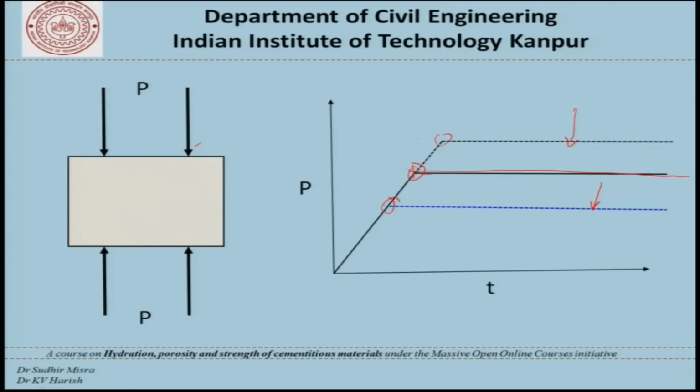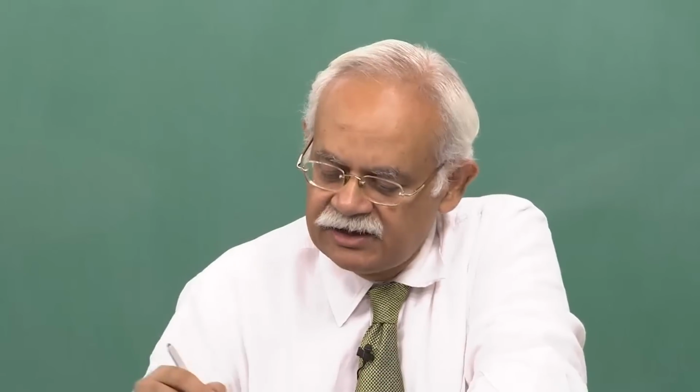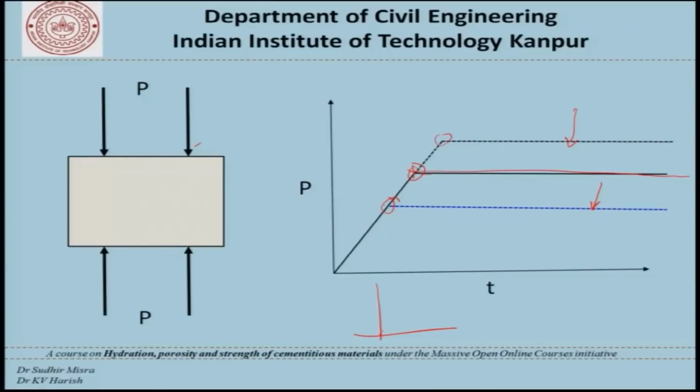So the stress strain curve as we normally see, which is the kind of graph which I showed you like this, is determined under monotonically increasing load. Do not wait for too long. How long we wait and so on, that's immaterial, and that's why in fact the codes tell us the rate of load application.